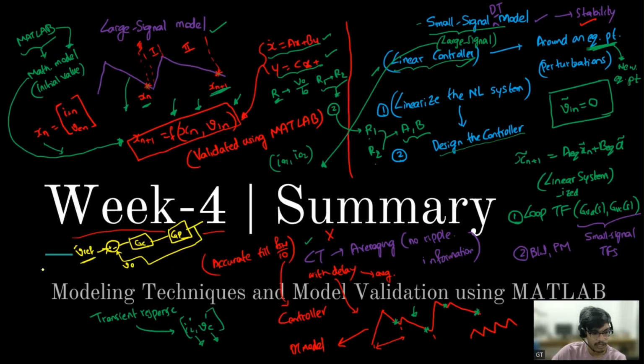Initially V reference is say 1 volt. Now I have made it 2 volt. So V perturbation is 1 volt. Now there will be an error here. So the error will increase, and GC will try to change its output accordingly, so that V naught perturb, which initially was 0, now changes to 1. So V naught perturb becomes 1, and then the error becomes 0. So our controller ensures that the error is 0. If there is any change in, say, V ref or I naught, then accordingly it will try to reach that new steady state.